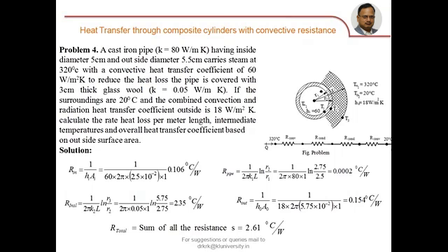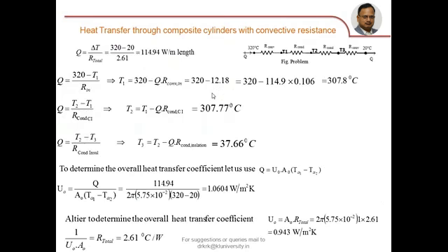As the thickness is small and thermal conductivity is high, it offers very low resistance to heat transfer, hence the temperature gradient is almost zero. That is the reason why you get almost the same temperatures at T1 and T2. Sometimes they may ask you to neglect this resistance by directly giving the outer surface temperature of the pipe.